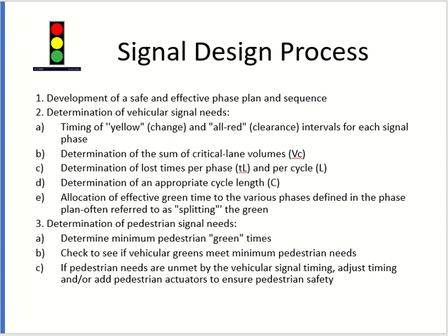The pedestrian time, is it equal or less than the time you are already providing for the vehicles? If it is, the pedestrian will cross with the vehicle, no problem. Okay, the signal will become green for the pedestrian. The signal will become green for the vehicles, the pedestrian will move with them, and it is enough time for him or her to cross. Okay, so if it is enough, you stop. If it is not enough, you have to increase the time according to the pedestrian requirement.